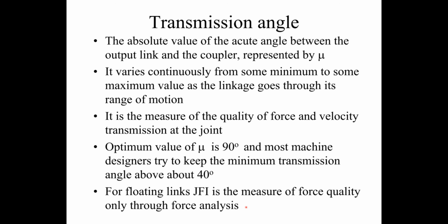So that's all for the transmission angle, and you can apply this transmission angle for any 4-bar mechanism you have built which is pivoted to ground. Link number 2 is the input link, and link number 4 is the output link.